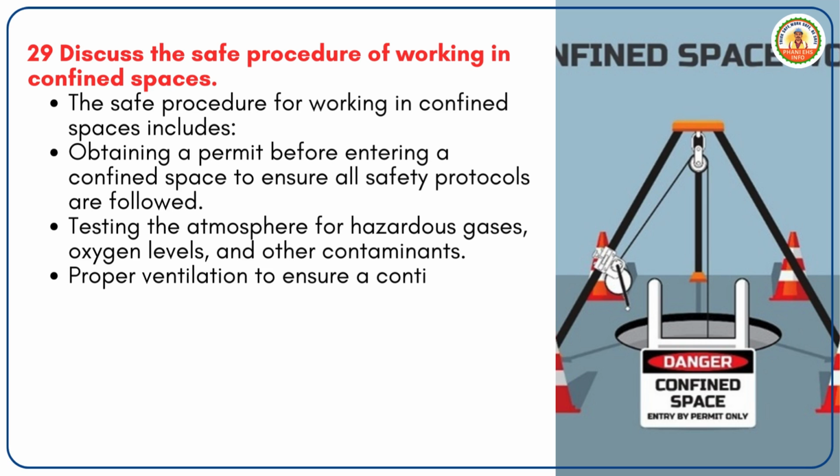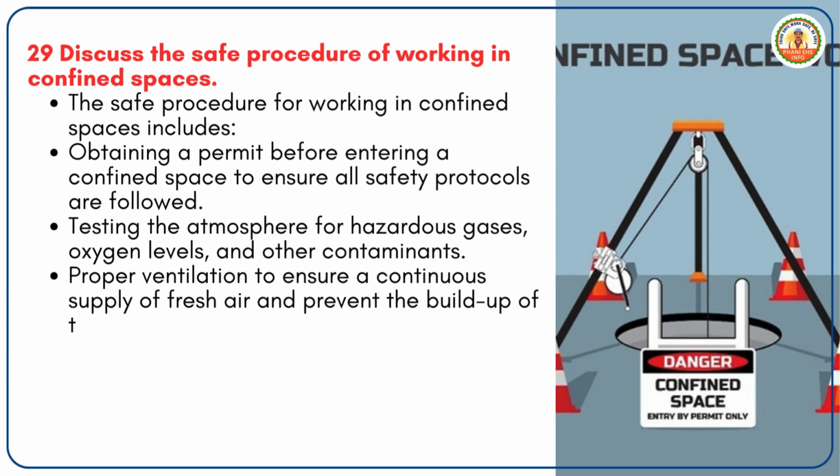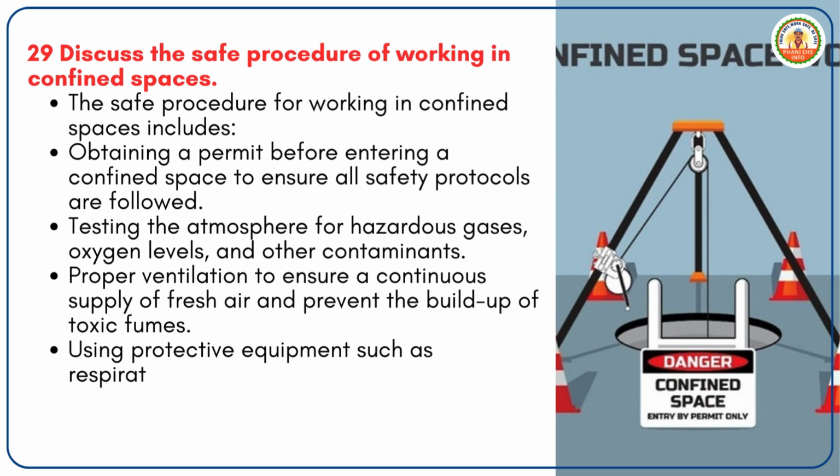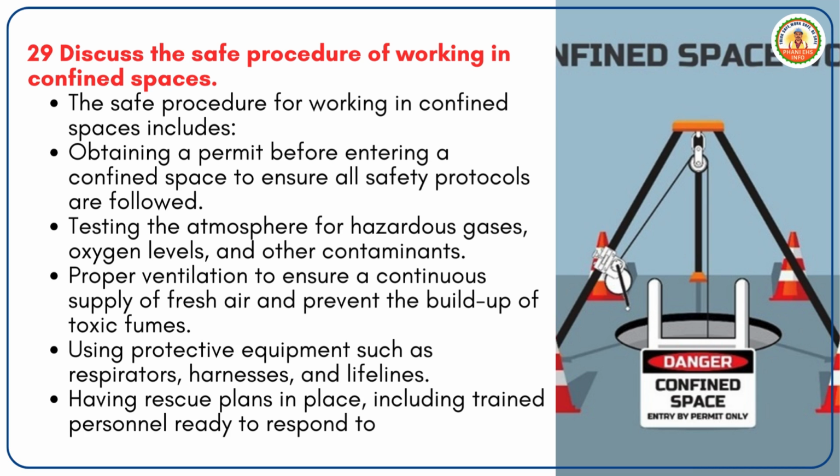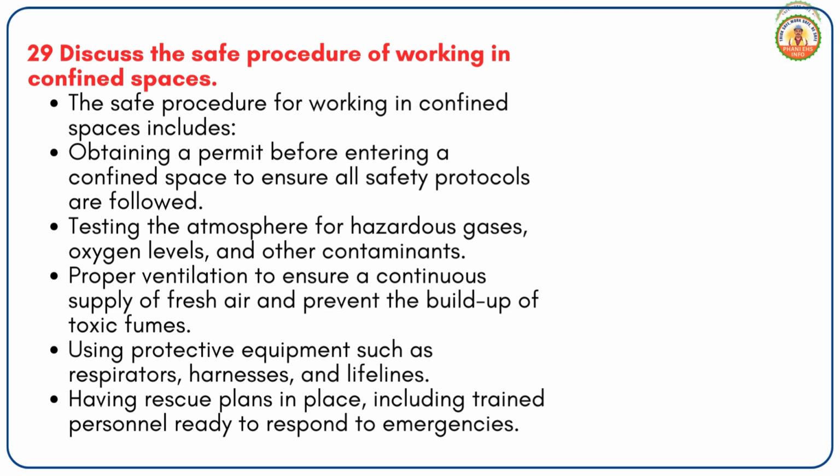Proper ventilation to ensure a continuous supply of fresh air and prevent the buildup of toxic fumes. Using protective equipment such as respirators, harnesses, and lifelines. Having rescue plans in place, including trained personnel ready to respond to emergencies.